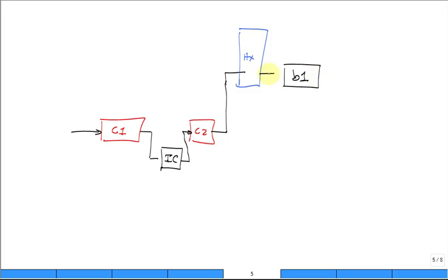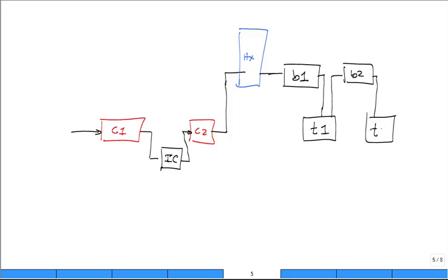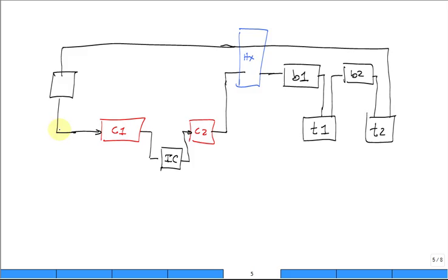Now the burner, let me sketch the whole thing out. After the burner, you put it into the first turbine stage. After the first turbine stage, you take it back out, you put it into another burner, burner 2, and then you put it into a second turbine stage. After the second turbine stage, you now try to get some heat out of it in that regenerative heat exchanger, and then you come over and you finally dispose of some energy to the environment. So we explained the intercooler. We already explained this regenerative heat exchanger.